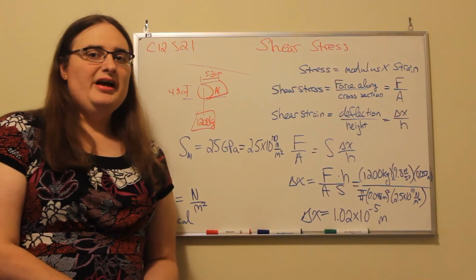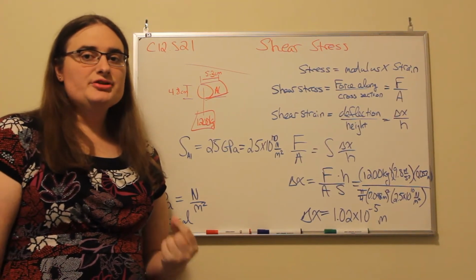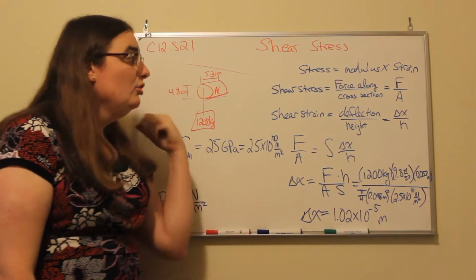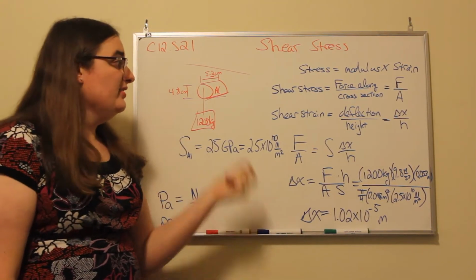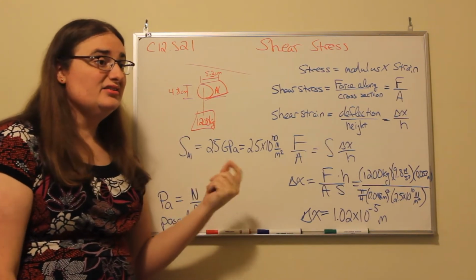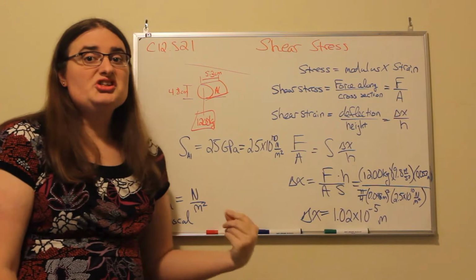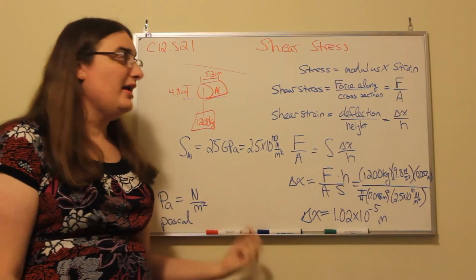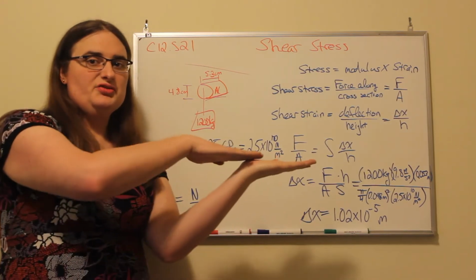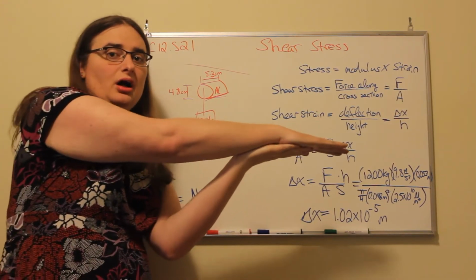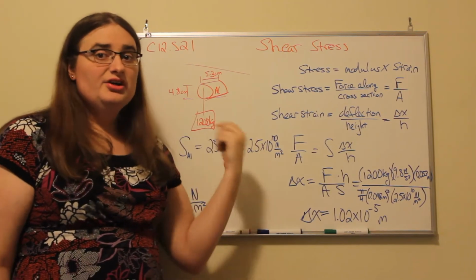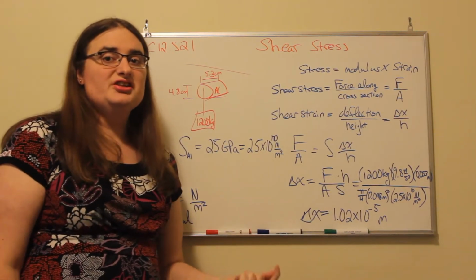Hi, this video calculates an example of shear stress on a post that's protruding from a wall. Now, with stress and strain, physically the definition is stress is how a force is spread across some area. So in the case of a shear, stress is a force that's applied along some sort of cross-section. And with a shear, the strain is the dimensionless response.